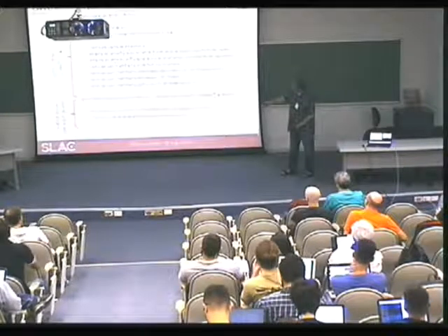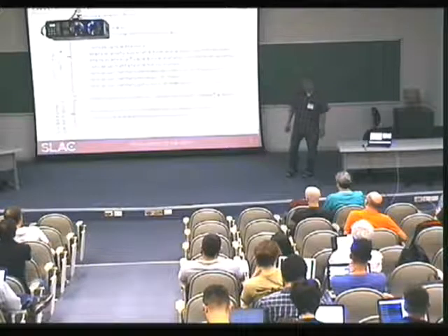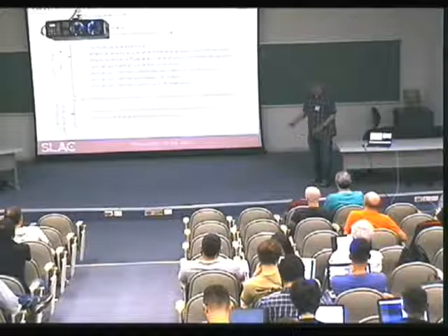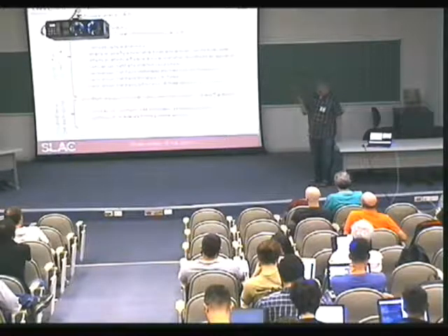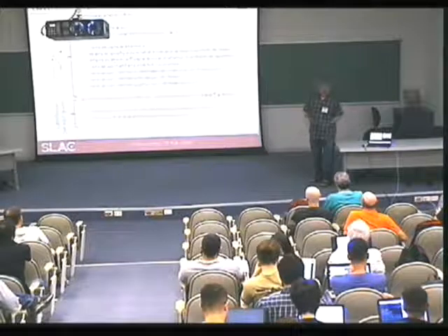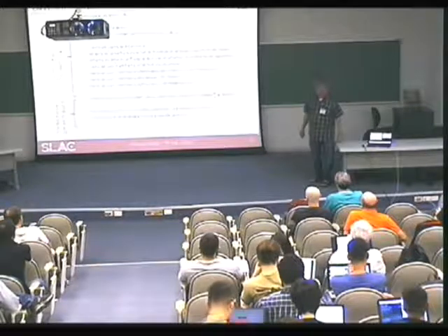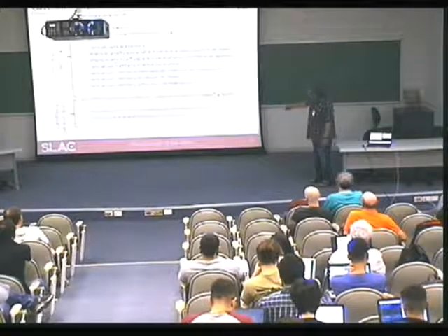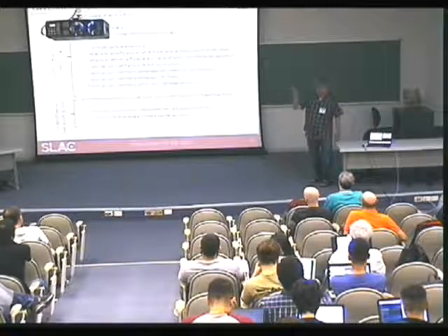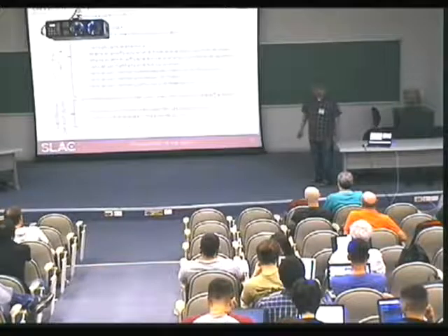G4RandomDirection is a really nice utility method of Geant4. It generates a unit vector randomized in 4π in a completely uniform way. Event by event, I just randomize the direction and shoot the particle.